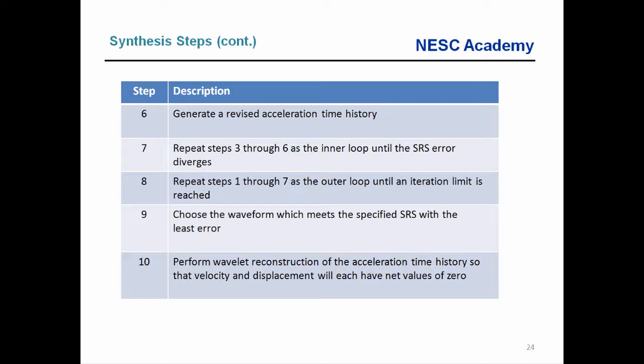So how can we get stable velocity and displacement values? Well, I'm sure there's some method where we could take that synthesized acceleration time history from step 9, and do some integrations and trend removals, and then differentiate back up from displacement to velocity to acceleration.